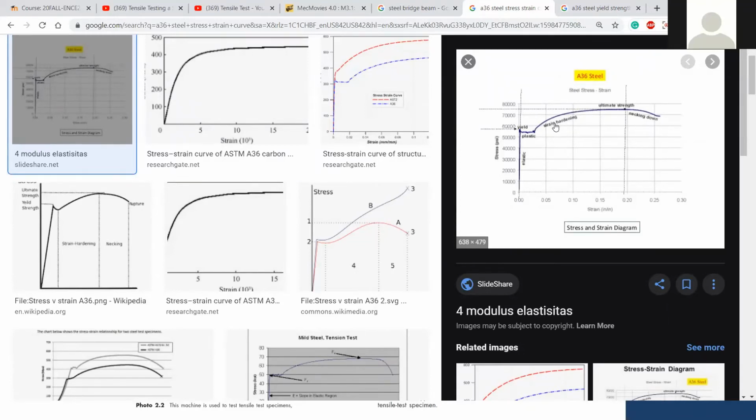So if the deformation is excessive, let's say 0.1 or 0.15, then I know that this material has already deformed permanently, and there are ways to retrofit it. There are ways to apply rehabilitation and fix it. But if your deformation is less than 0.02, you will intuitively know it is in the elastic region and it's good to go, and there is no problem with the member.